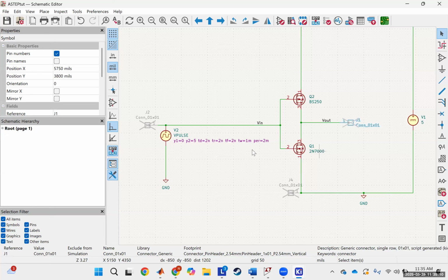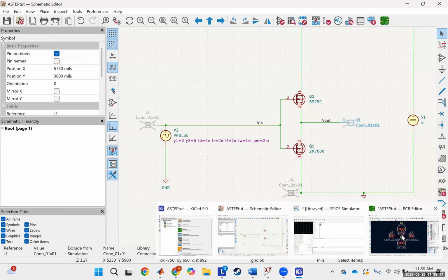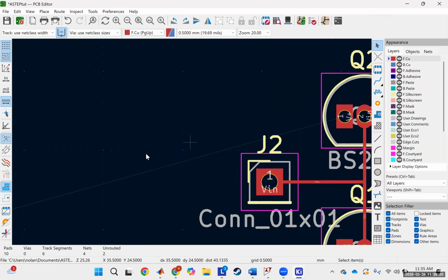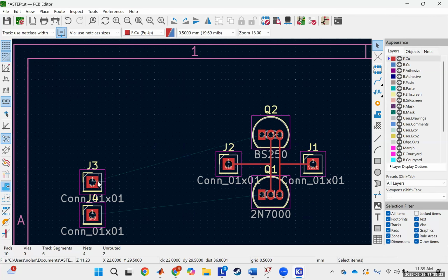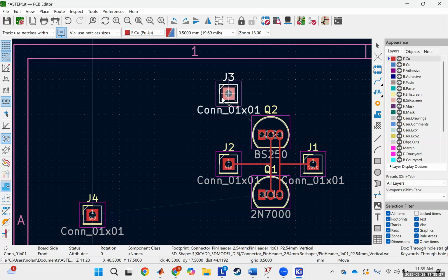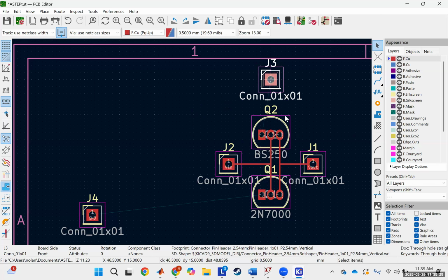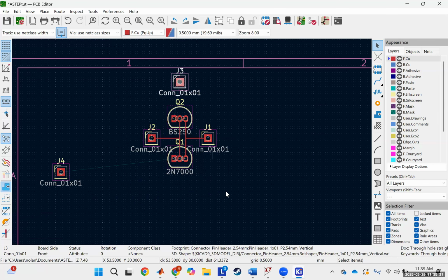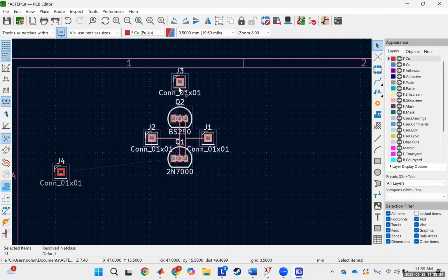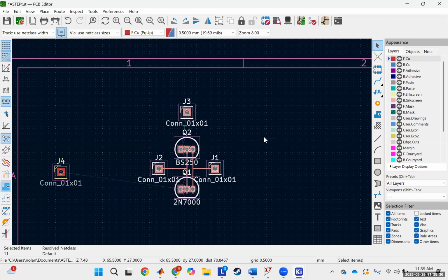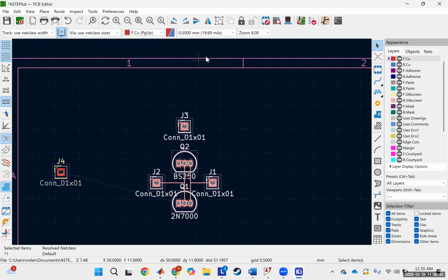Our inverter is done. But we always need to give our circuits power. So to give our circuit power, we're gonna grab these other two pins here, our V plus pin and our ground pin. And let's put this up towards the top for VDD or for our V plus. Also, to move multiple things at once, you can left click, drag, and just move it if you want some more space so that we don't go over the edge.